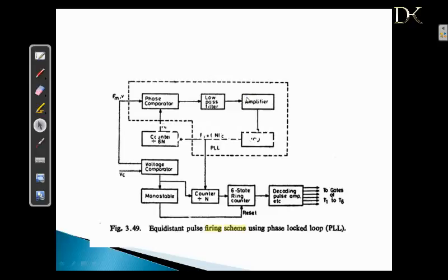The PLL maintains the output frequency of the VCO at exactly 6n times the main frequency. In the event that the main frequency FM changes, the output frequency of the VCO also changes. The frequency FC tracks the main frequency FM. The output frequency of the VCO F0 is divided by 6n to obtain FC, which is compared with and maintained at the same frequency as FM. There may exist a phase difference between FM and FC, but this should be as small as possible in order to minimize error in the firing angle.